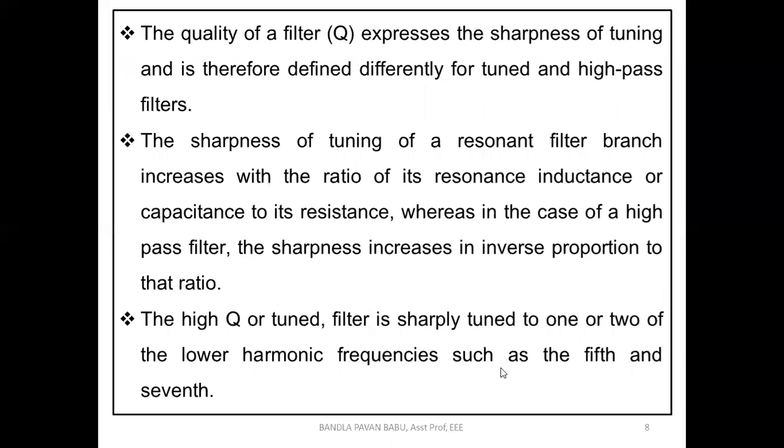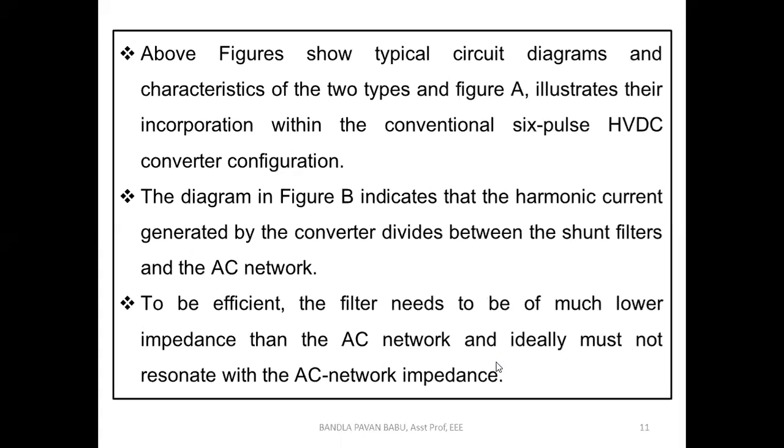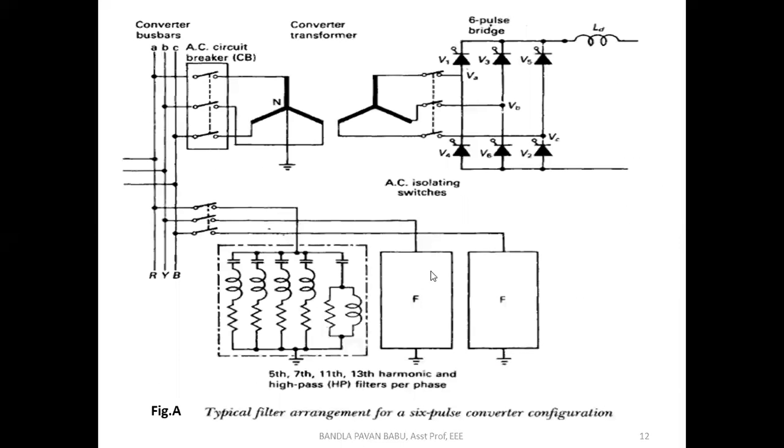Let us see from this figure. Look at this figure. This is the HVDC converter station. At the AC side, either it may be before rectification or after inversion, we have connected the filters. If we calculate all the filters which are shunt connected, we will have an idea to which extent we can compensate the reactive power by using these filters.